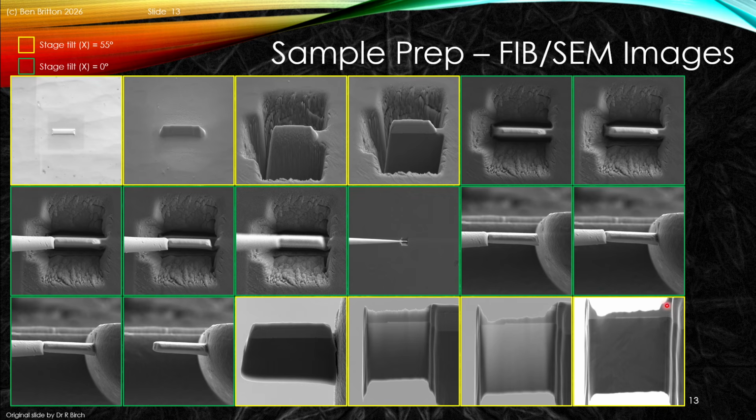We can also use the FIB-SEM as a sample preparation method, and so this is an example that we'll delve into in a lot more detail later, where we've put a capping layer on top of a steel to produce ultimately a 5 micrometer cross section, where we can look at that microstructure with, say, TEM methods. So here we do the electron beam cap, ion beam cap. We've cut trenches around the region of interest. We've cleaned up those trenches to give us a beautiful, cleaned up lamella.